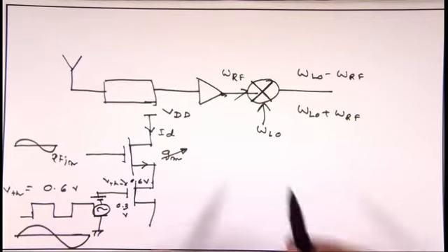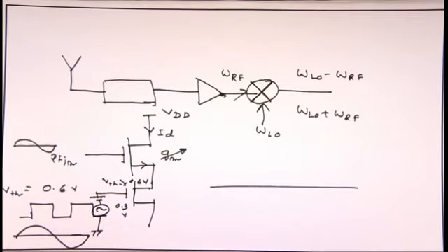So, what will happen? This signal is called the local oscillator input signal, and it is under your control because you have rightly known how to design a VCO. So, typically you are giving a swing of, say, 300 millivolt peak to peak, 400 millivolt peak to peak, or 600 millivolt peak to peak, like that. It is up to you. So, this is no longer a small signal, it is called a large signal, and the transistor will act as a switch.